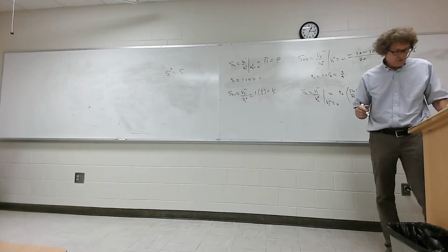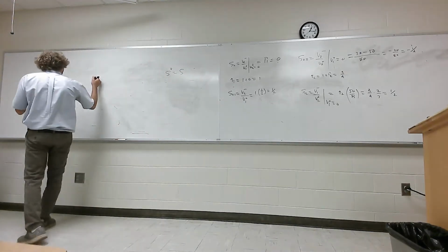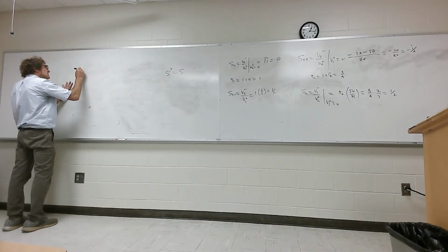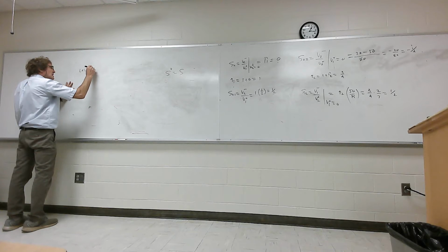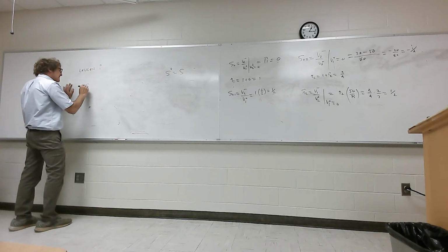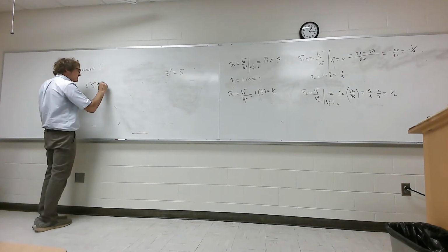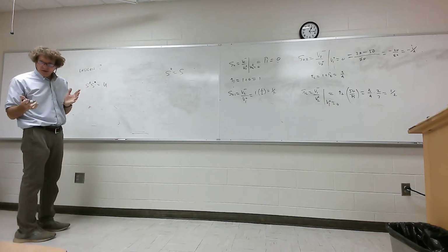He has it: S transpose times S conjugate is the unitary matrix. So if you want to check out that data you measure, if you're wondering if it's lossless, then you do this. Simply take S transpose and then multiply that times S conjugate. And if that's the unitary matrix, it is in fact lossless.